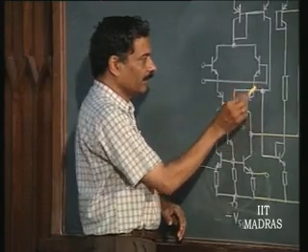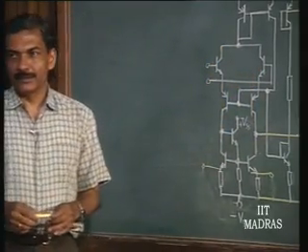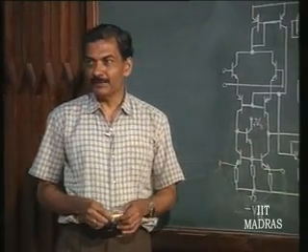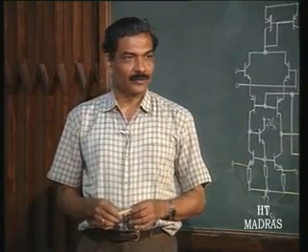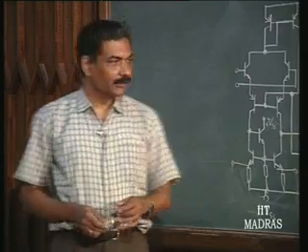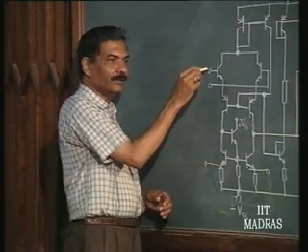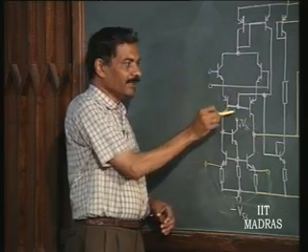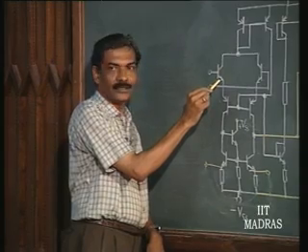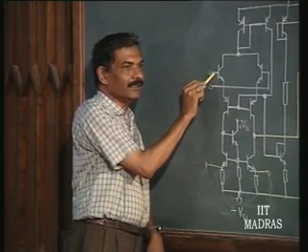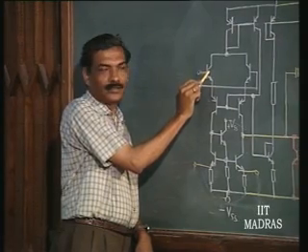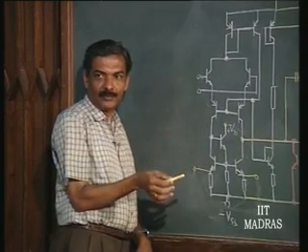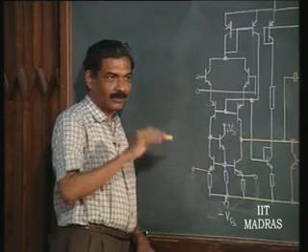Now, this structure here, let us understand. We said if we have decided to use NPN current mirrors, we must drive it by means of a PNP pair, but we do not have a good PNP pair. So, what do we do? We now use a cascading of NPN with PNP. In such a manner, now you can see, as far as signal is concerned, okay, the base current of this is NPN base current. So, emitter current is going to be definitely beta times that. So, the effect of input impedance etc. is going to be retained, okay, because of good beta.